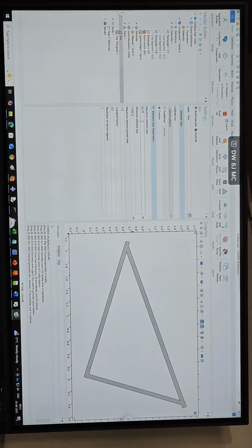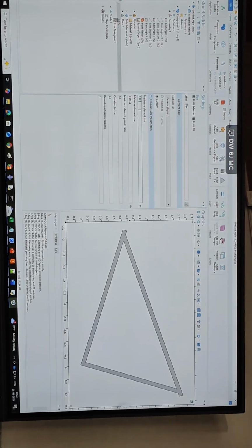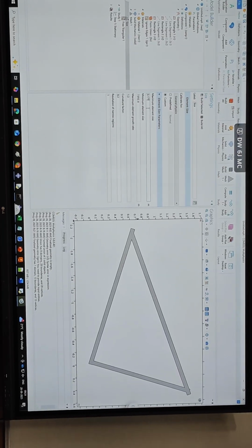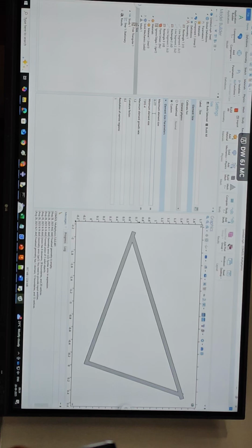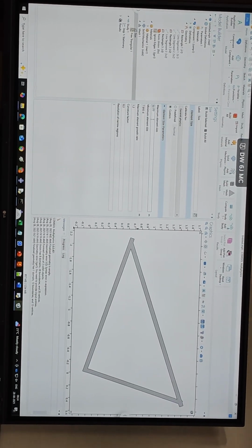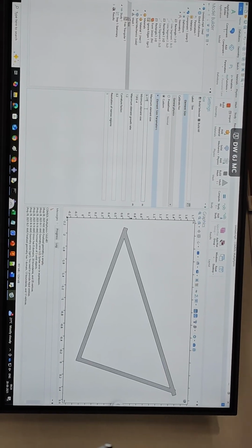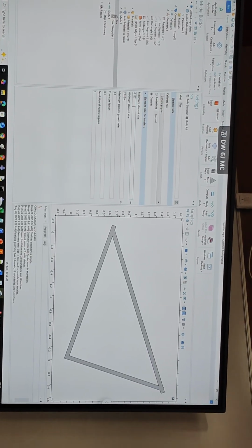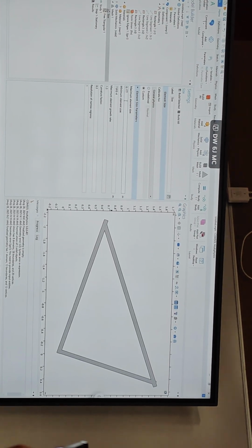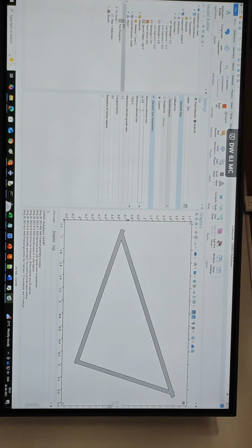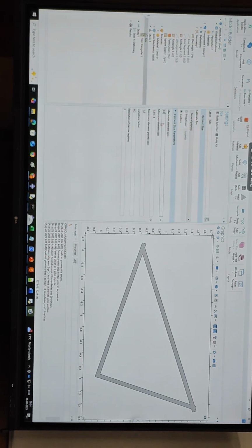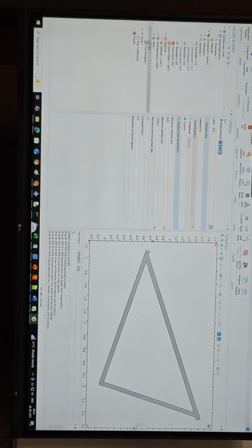So now I want my maximum element size to be restricted to a value which is reasonable within this given thickness. Because we took 0.06 as a minimum dimension, and here I told you, right, it's explicitly enforced in meters. So this is what I said will happen if you don't put a unit in the start. So if I put mm in the start, right, it will override this meter here. So if mm was explicitly defined in parameters, it will override the GUI's unit here. So that is something you have to keep an eye on in Comsol. So now over here I'll put, let's say 0.1, and I'll say build order.